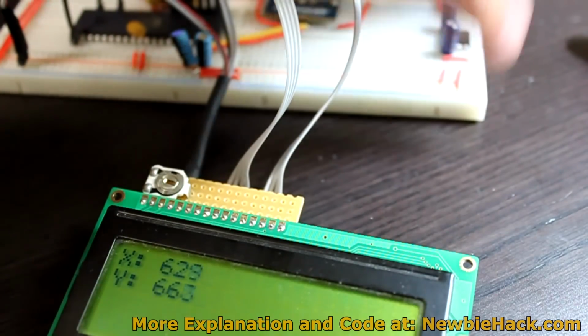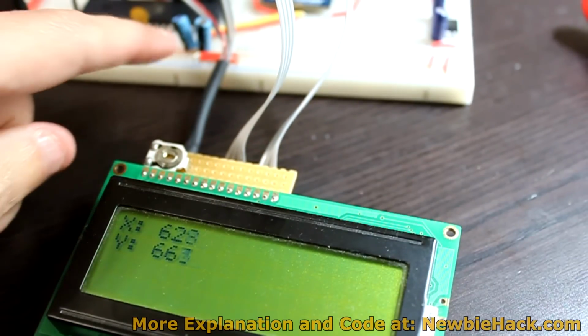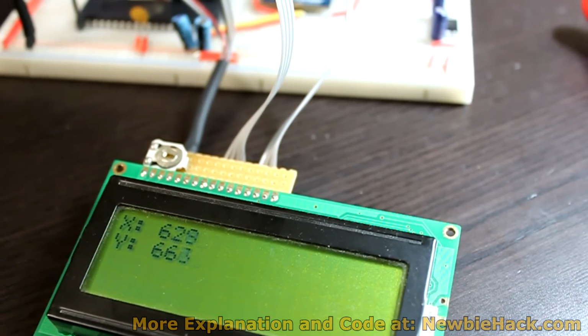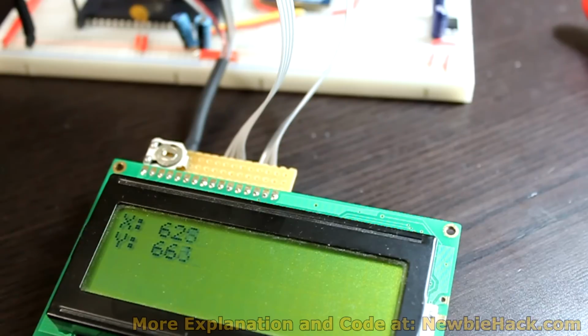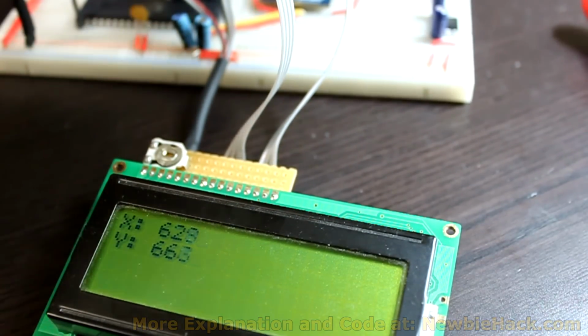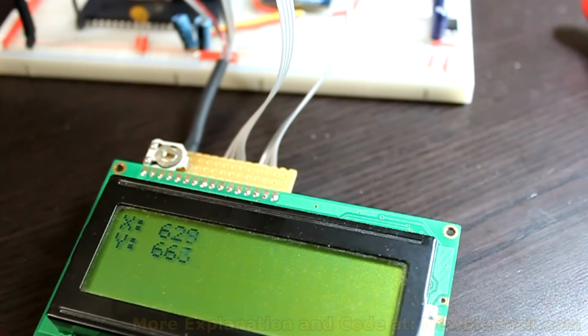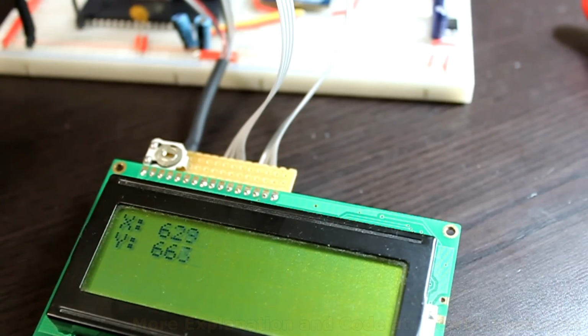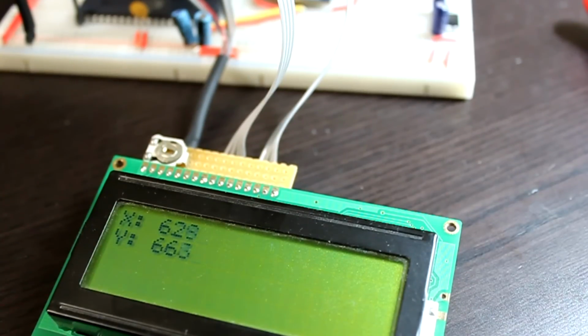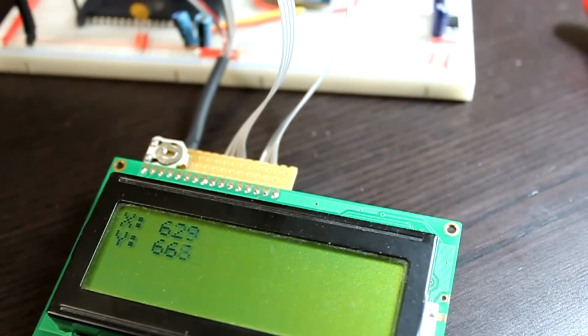So we have successfully connected our channel 0 and channel 1. We've programmed it so they are showing independently on the LCD. And if we wanted to increase the channels, all we'd have to do is wire the devices to the other channels and increase the number of case statements that we have in the switch. So that is how you use multiple channels in ADC.